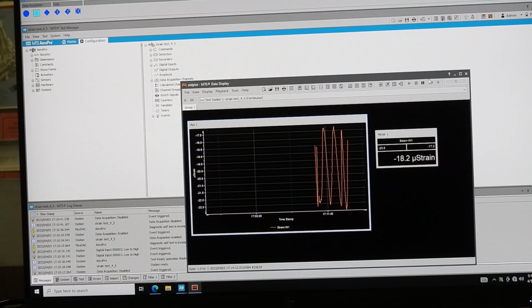It's saying, okay, if I'm above this level, say I'm on. If I'm below this level, say I'm off. But we don't want to implement a pull up or pull down, because now we're using an analog input. If I start putting a pull up or pull down in, I'm going to screw up my analog input. So it's a smart DIO. Use what's available there, the ADC circuitry that's there, to provide the digital input functionality without having a dedicated digital input.